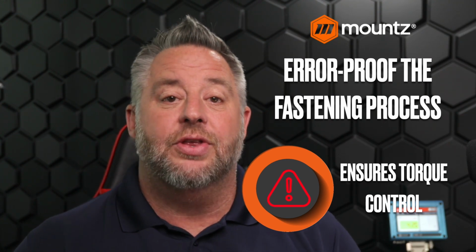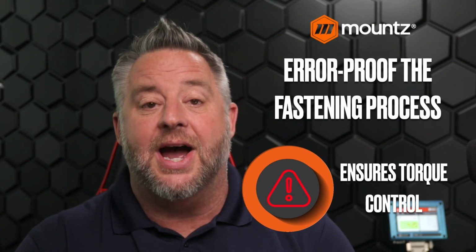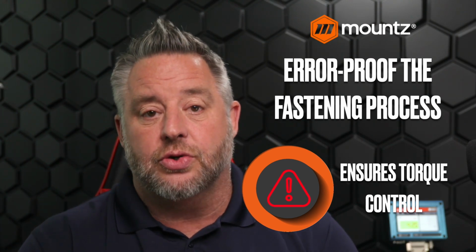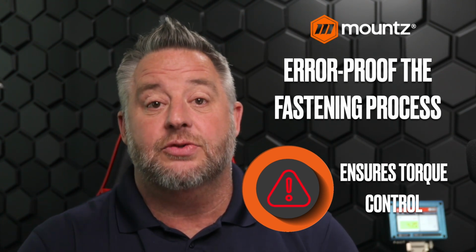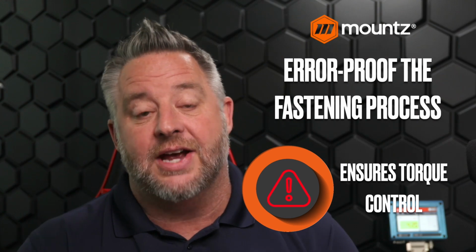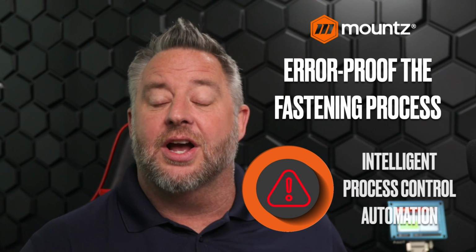We want to make sure that our clamp force is correct, and we get that correct clamp force by ensuring that our torque control is correct. And in some of the other instances, we want to make sure that we hit all of those fasteners to ensure that correct clamp force.